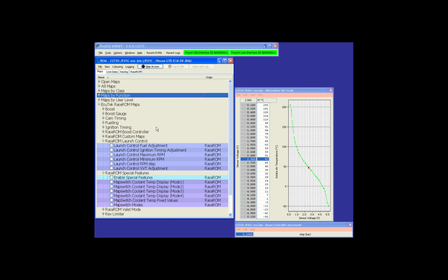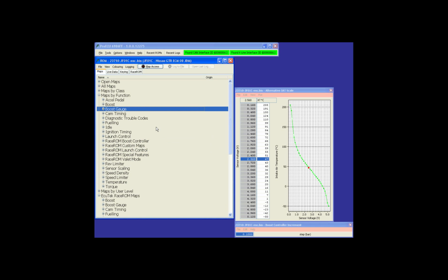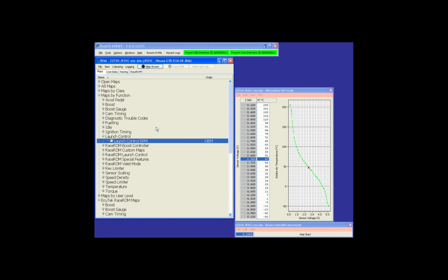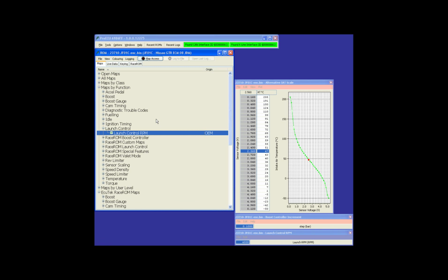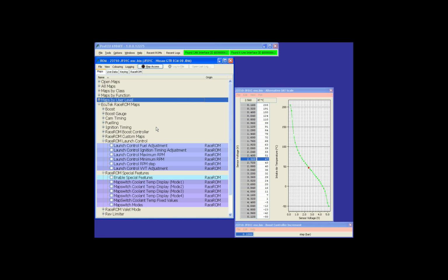Let's have a look actually. So this is a 2008 JDM STI. When we go to launch control, RPM is 4,500 on our car by default. So once we go into the special launch mode, and you know when you're in it, we can adjust this launch RPM, therefore adjust the launch torque, increasing and decreasing the torque, more or less slip, less stress on the drivetrain.